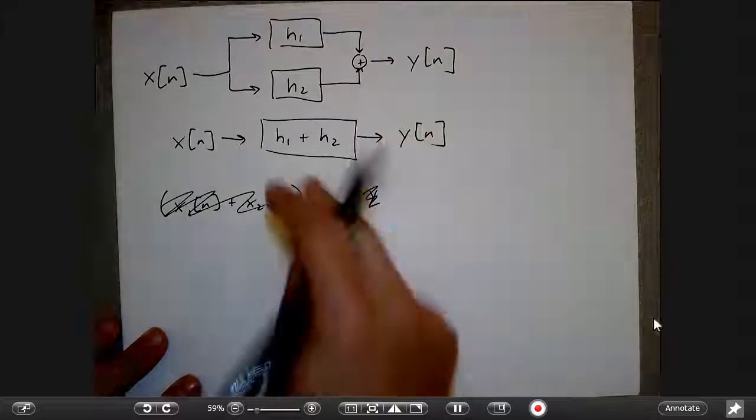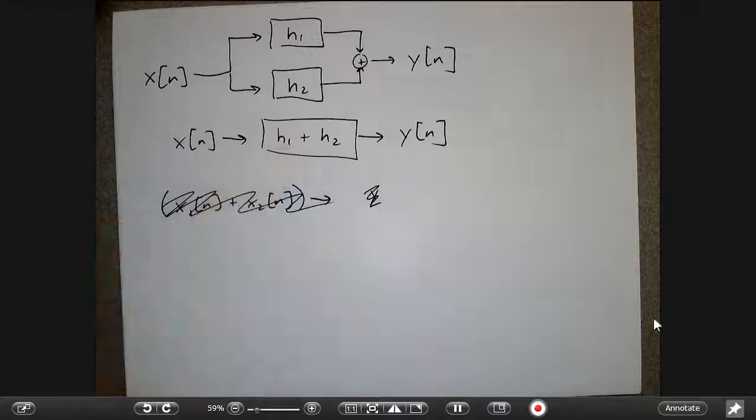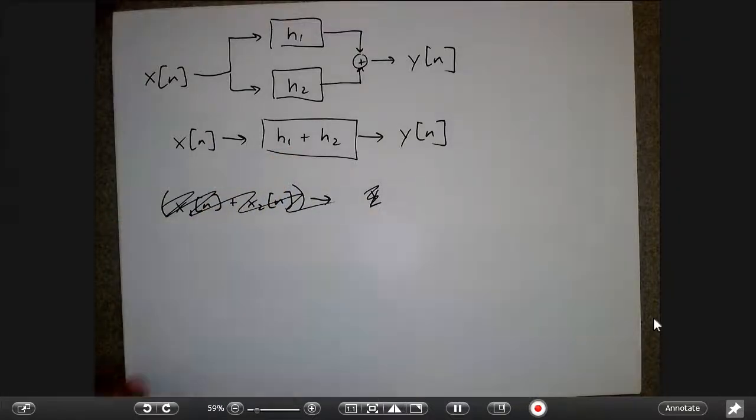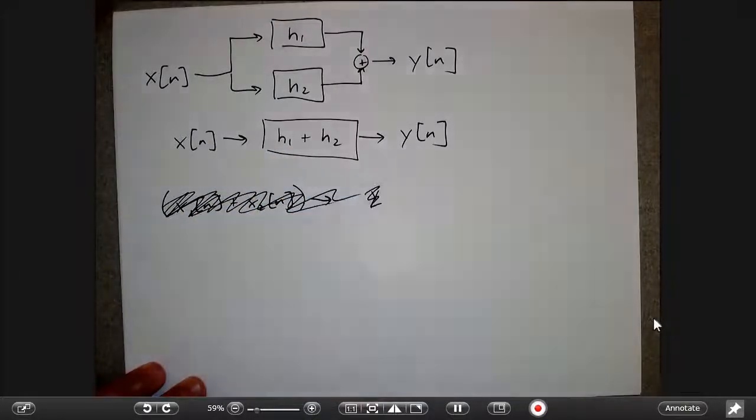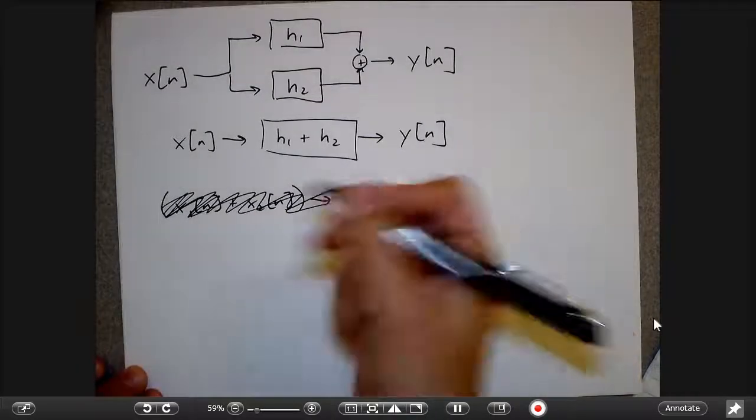This is basically more like saying what happens when I put these systems in parallel. So again, like my graphic equalizer, this is like saying that I can get the effective response of my graphic equalizer by creating a combined impulse response from all that stuff. Okay. And that can be used to break up convolutions that might otherwise be a pain to do. Okay. All right.